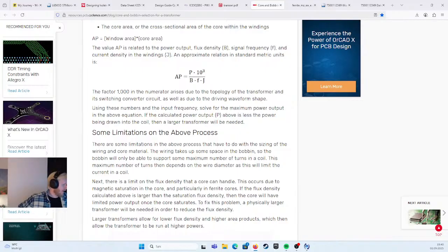So the inductance of a transformer refers to mutual inductance, the ability of a changing current in one coil to induce a voltage in another coil. Transformer's inductance also includes magnetizing inductance and leakage inductance, which relate to the primary coil's ability to create a magnetic field and a flux that doesn't link the secondary coil, respectively.